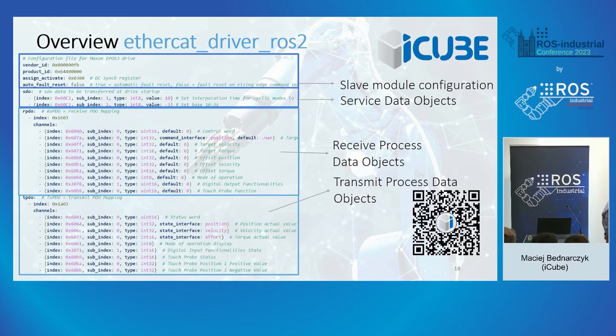And here, as you can see, the binding between the states that you declared in URDF and the different drive components, which is, for example, this register here is the actual velocity of our motor. Basically, you declare it here using the state, binding them by name together with what is in the URDF.